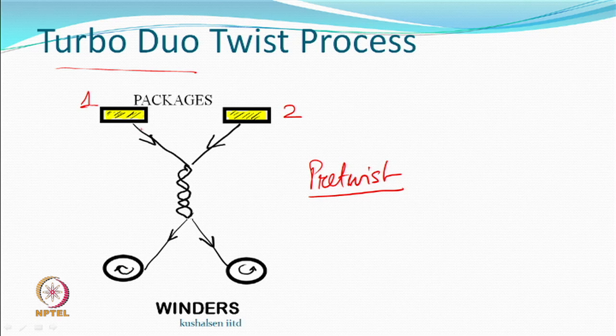So, what you have is, actually you should have a feeding mechanism. Why is this feeding mechanism required? What is important is that if you do this and just keep pulling, as long as the yarn is being fed, you will suddenly find this twisted zone just remains there. The new yarn comes in the zone, gets twisted, and as it gets out of the zone, that portion where the twist is there just stays there, maybe a little bit of vibration based on what you do.